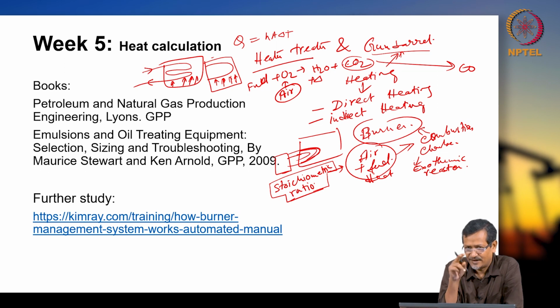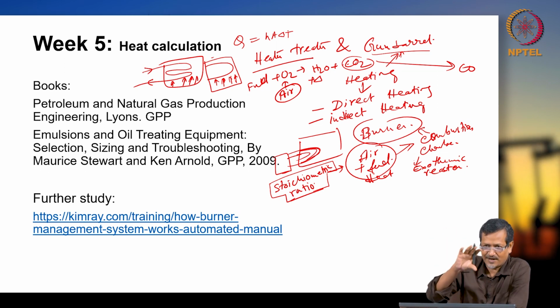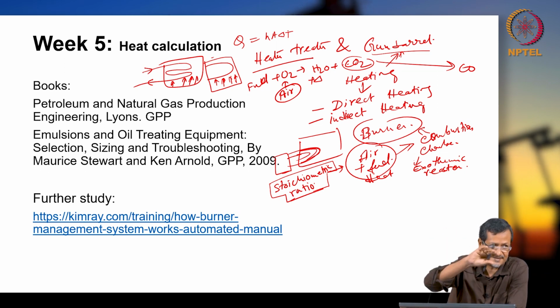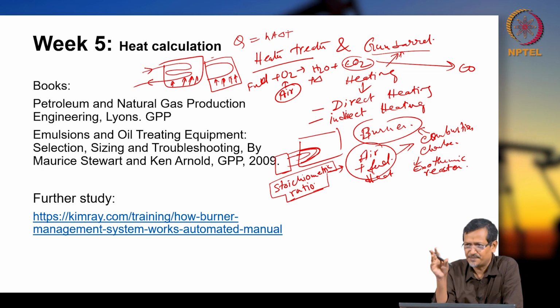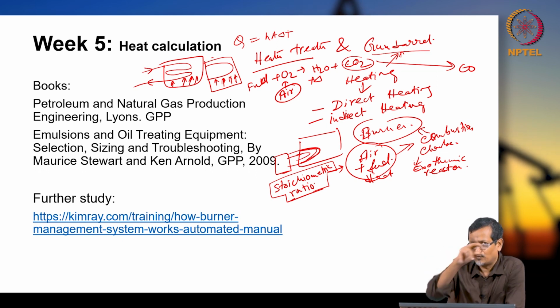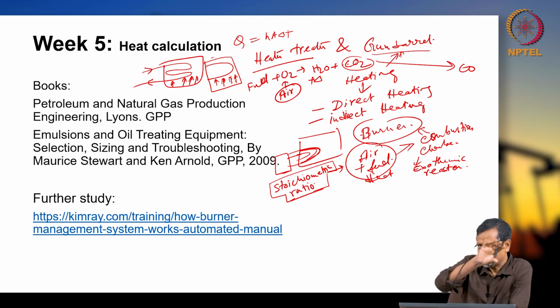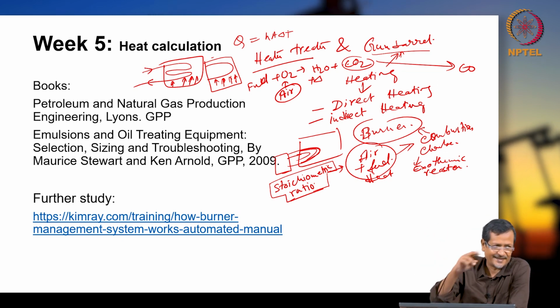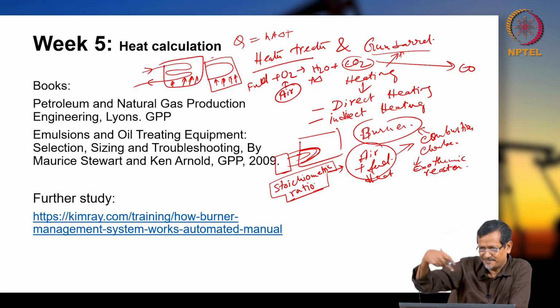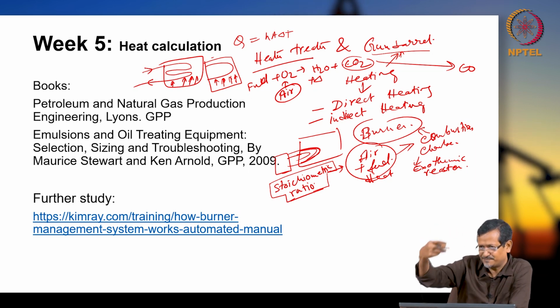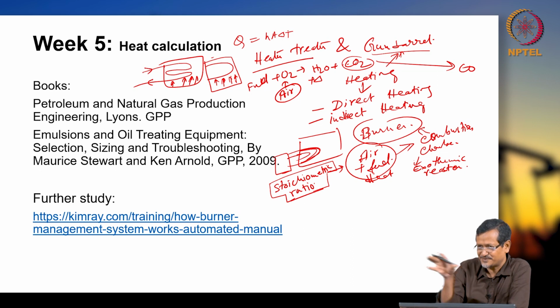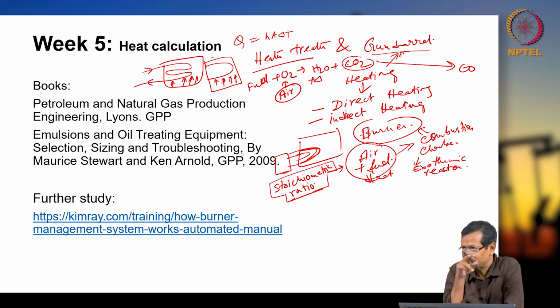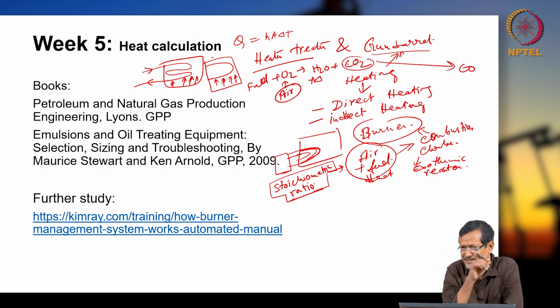A means area of the pipe, surface area, how much contact area there is, and delta T is the temperature difference. Now if you have a one-pass pipe, the total surface area of the pipe is low, but if I have multiple passes, then it is L times pi d. Pi d is the perimeter, times L, so that is the total surface area. So multiple passes mean the total area increased, so my heat transfer rate increased.